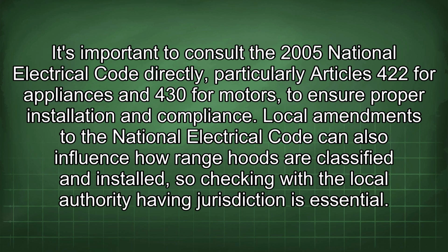It's important to consult the 2005 National Electrical Code directly, particularly Articles 422 for appliances and 430 for motors, to ensure proper installation and compliance. Local amendments to the National Electrical Code can also influence how range hoods are classified and installed, so checking with the local authority having jurisdiction is essential.